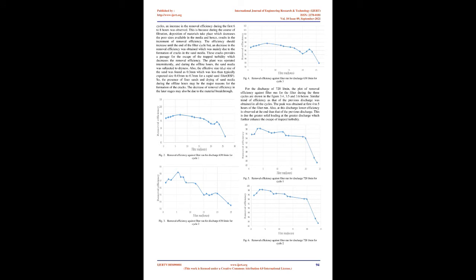The major characteristics of the water of the well is observed as electrical conductivity of 932. The different treatment units of the project are as follows. Aerator. The aeration system consists of 5 number of tray aerators.